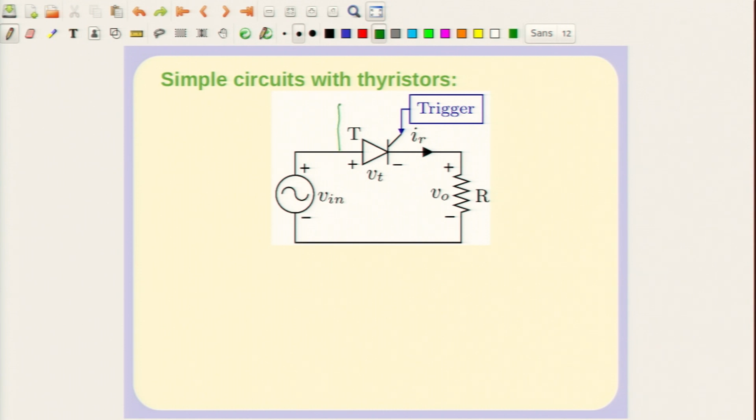If you have an electrically triggered thyristor, then the supply of this is actually derived from this, but of course, this may contain electronics which themselves require power supplies. So, usually you will be using some kind of transformer here for isolation purposes. Okay. So, that this circuit's potentials do not matter; for example, if this is a circuit which is grounded, and the electronic circuit also has to be grounded, but you wish to have freedom in which point you want to ground the electronic circuit, then you would require an isolation transformer. Okay. So, this is an important point which you should notice.